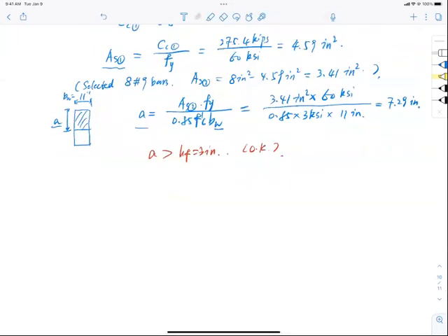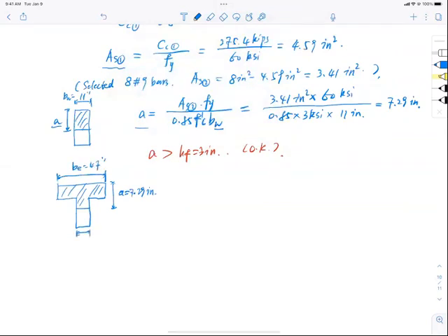You look at the section, you say, finally, I have a beautiful T section, and my T section has the compressive zone size of A and have the flange fully developed, and this is 7.29 inch, A equal to 7.29 inch. And now BE is 47, nice and easy. And BW is 11 inch where I'm at it, and that is my compressive zone.